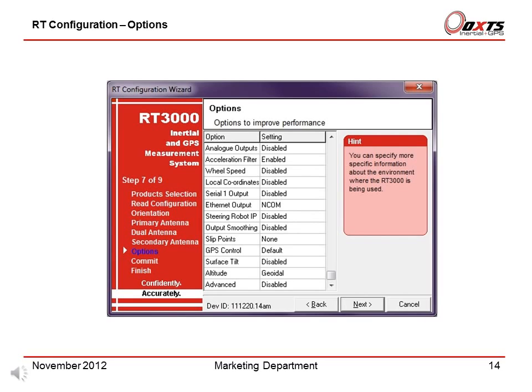Altitude. The RT can output altitude compared to the WGS84 ellipsoid, compared to the geoid, or a constant offset compared to the WGS84. By default, the RT outputs altitude compared to the geoid. On the RT3000 or the RT4000 products, the EGM96 geoid is used.